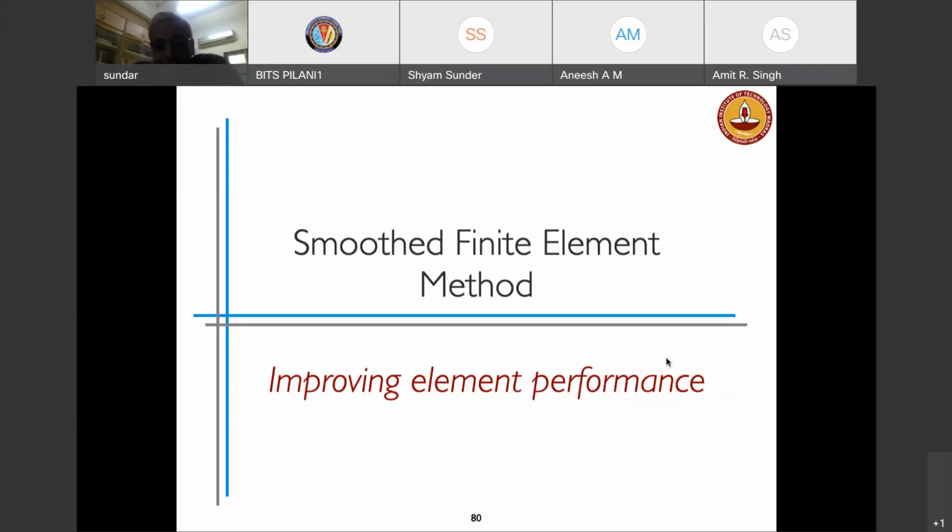So of course we can now use the polygonal finite element method, but then you need to change your meshing algorithm, and also most of the finite element code has to be modified for you to be able to use the polygonal finite element method or any other technique. So the idea was, can we use existing elements but then improve the performance of them? For example, it was mostly focused on using triangles or tetrahedrals as a base element and improve the performance of the element, right?